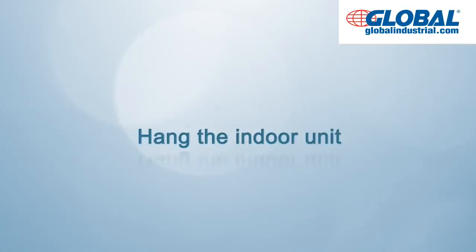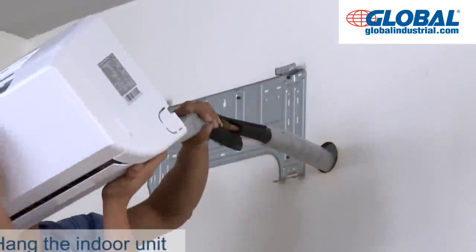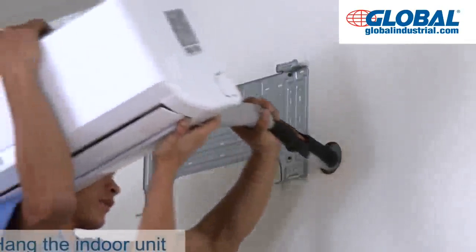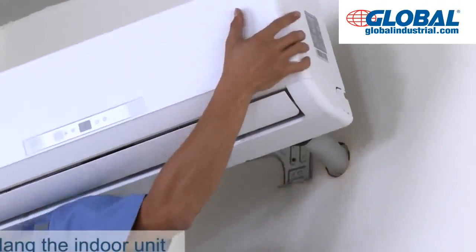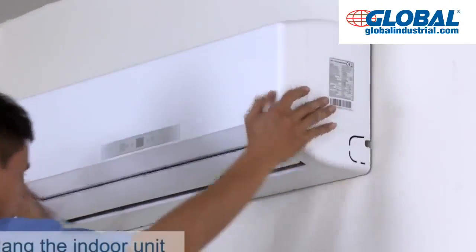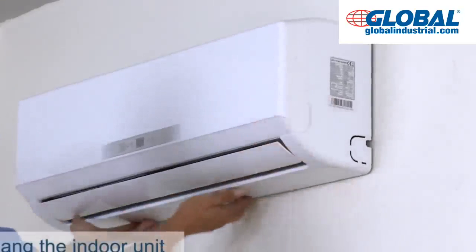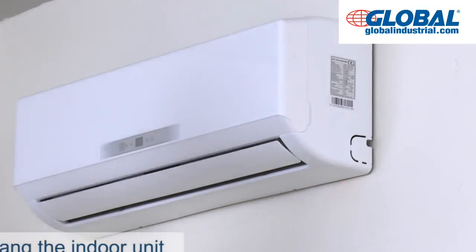Hang the indoor unit. Copper pipe and connecting wire after wrapping are threaded slowly through the wall hole to prevent from colliding with the wall or bending. Hang the indoor unit on the hook of mounting plate. Insert the lower part of indoor unit into the groove of mounting plate.